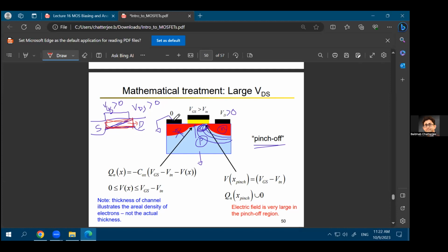And the other way is from the idea of depletion regions. The depletion region will not have the majority carriers, which means that it will be depleted of the electrons that you are trying to create under the channel, or under the gate.